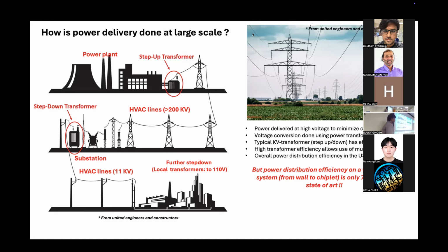One important thing is if you search what is the energy efficiency of the US power grid, it'll say something like 30%. But that is because they are taking into account the efficiency of the power plant itself. The power plant is badly inefficient because the generators are not very efficient. But if you just consider the distribution and the power conversion, that's close to 90 to 95% efficient.